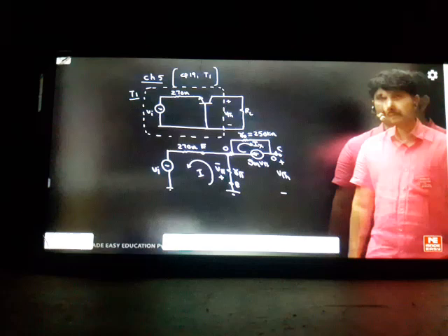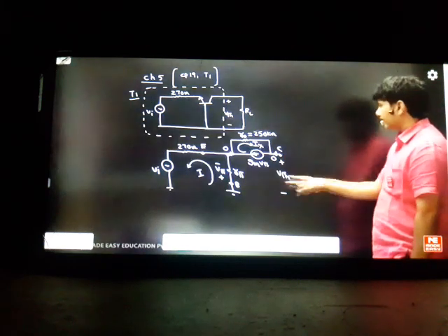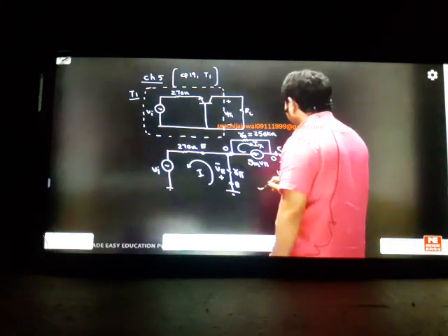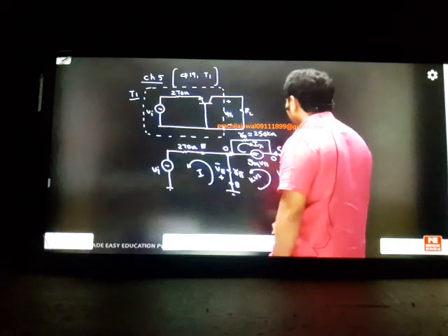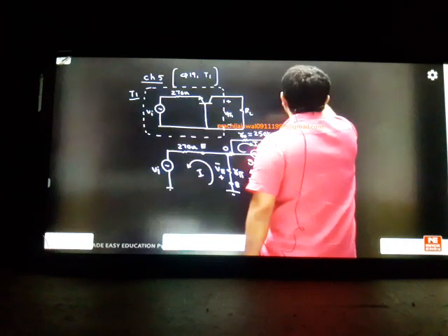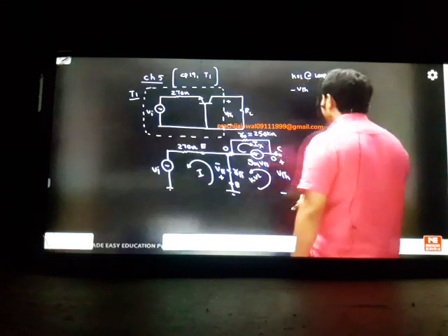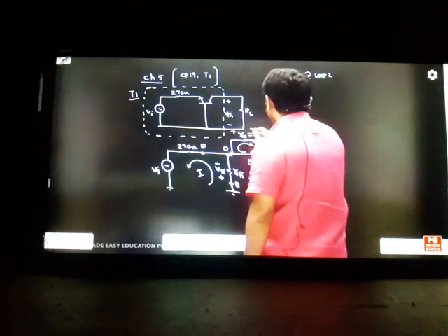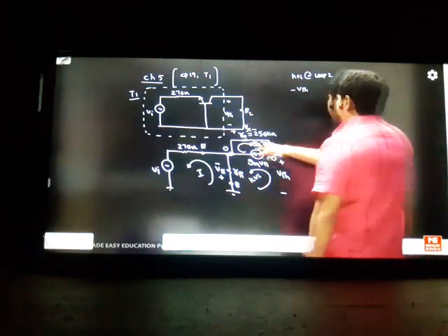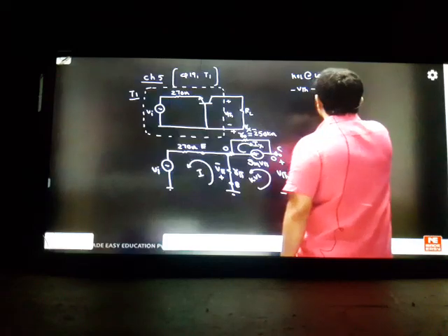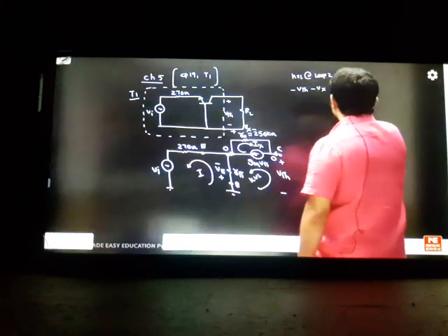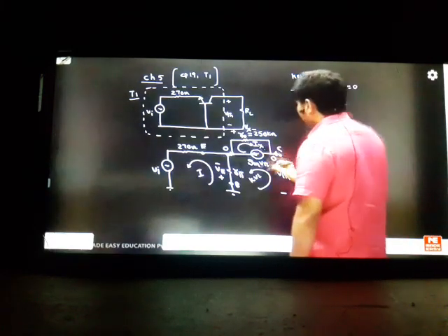So let us have KVL, VThevenin in terms of Vi. You have to find this answer. How to find VThevenin in terms of Vi? After writing the model, can we have here one KVL will apply? KVL at loop 2 I am applying. KVL at loop 2, it is minus VThevenin. This will become a plus minus Vx will be there here. Some voltage drop is there here by this current source. So it is minus Vx. Current is going in this direction. So minus V pi should be equal to 0. So this is my outer loop equation.